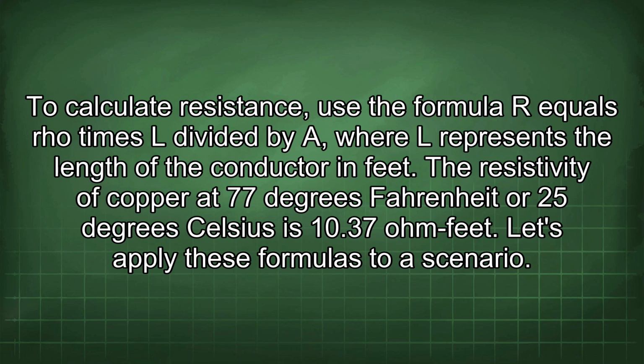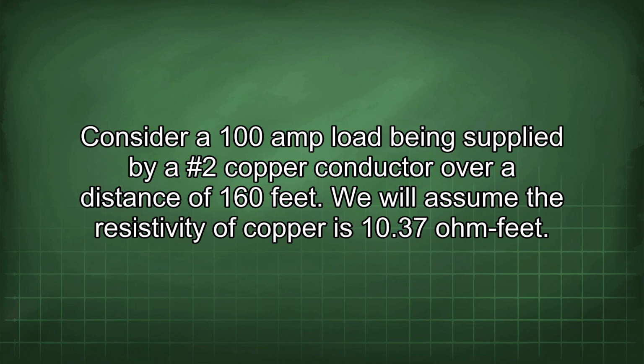Let's apply these formulas to a scenario. Consider a 100 amp load being supplied by a #2 copper conductor over a distance of 160 feet. We will assume the resistivity of copper is 10.37 ohm feet.